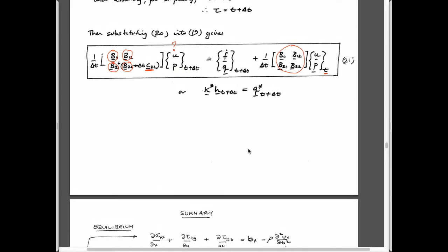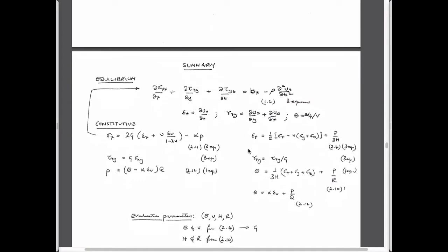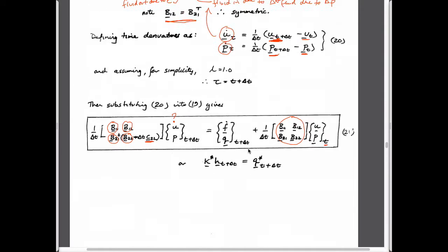So it's kind of complicated and involved, but the main things to realize are that we're just taking two expressions. We're realizing that initially if you solve them in COMSOL or anywhere else, they're unlinked, and you want to be able to make them talk to each other. You want the displacements in the solid mechanics system to talk to the fluid pressure changes in the flow problem, and you want the fluid pressures in the flow problem to talk to the evolving displacements in the element. Nothing more than that. Depending how you think about these systems, certainly that's one way to do it.